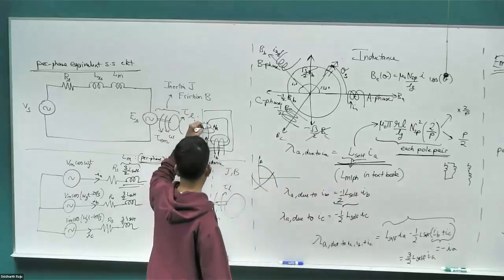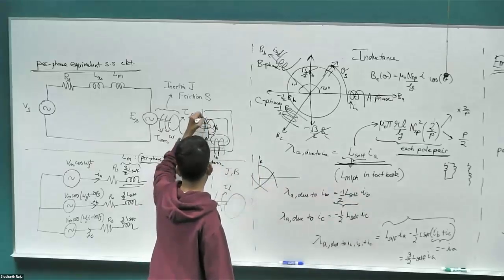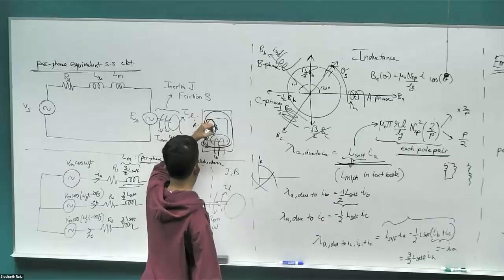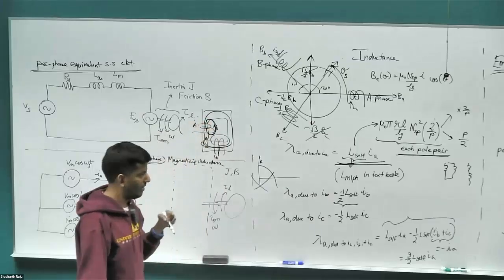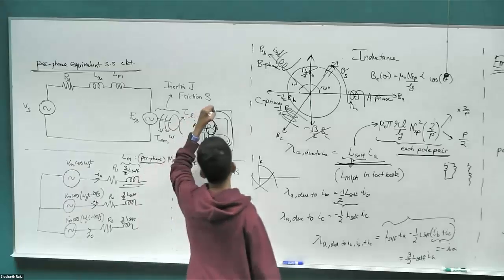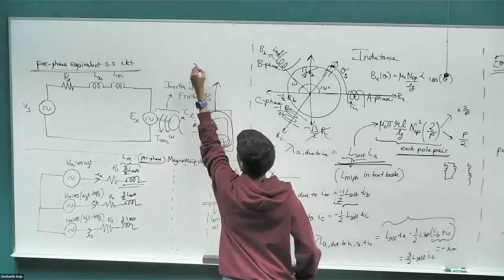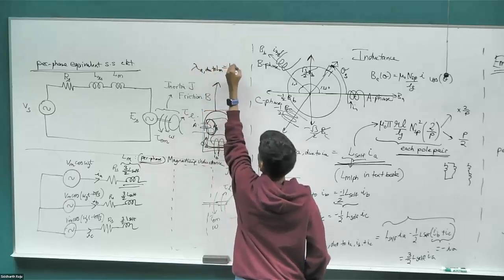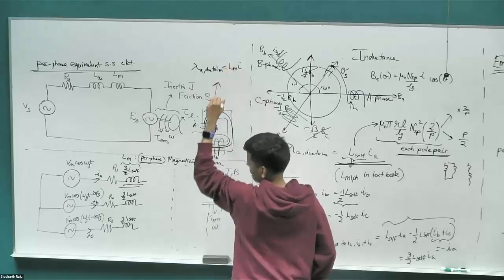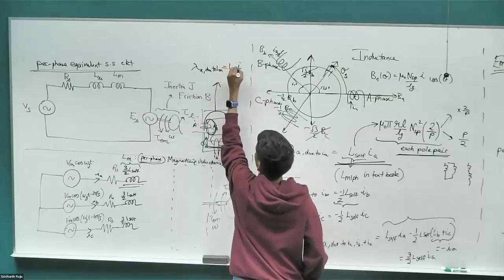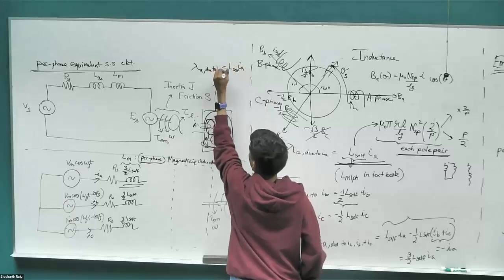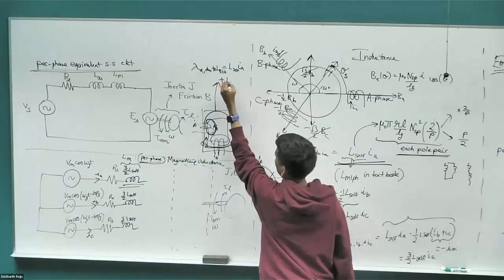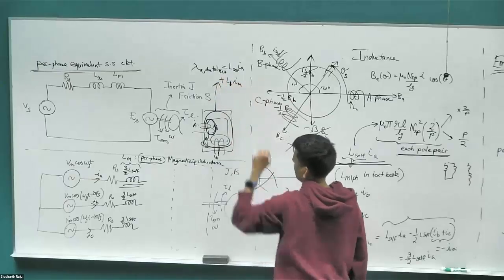So again, here if you have currents in the A phase, it is going to set up a flux which goes across the core and links to the other coil. And it's also going to have a flux component which is going to leak out and not couple with the other coil. So we're going to introduce another term for that. So this is lambda A due to Lm, which couples to other coils, L self times Ia. And in addition, there is something that leaks out, which we are going to call leakage LL times Ia.